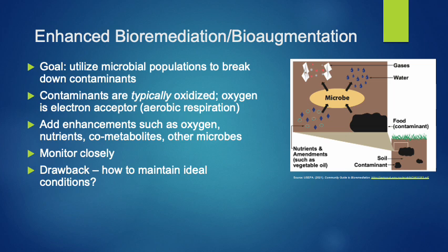In some instances, there may be a limiting factor in the potential for bioremediation, and enhancements need to be added, either through oxygen, nutrients, or co-metabolites. In some instances, microbes can actually be introduced into the subsurface. In this instance, it's referred to as bioaugmentation.